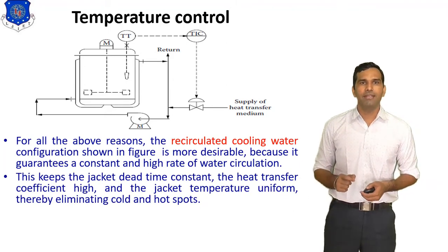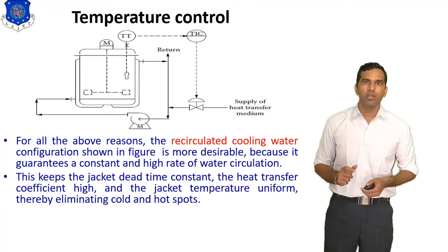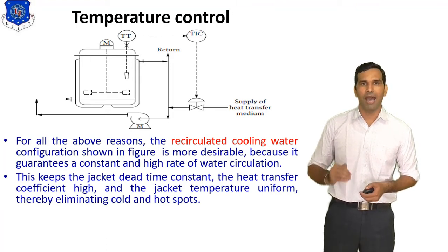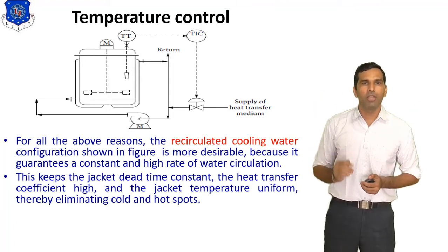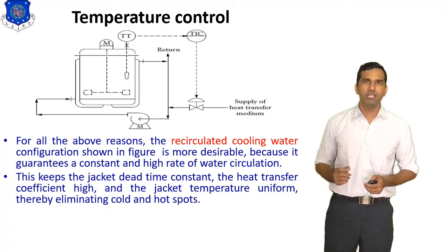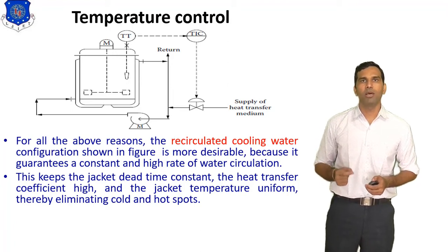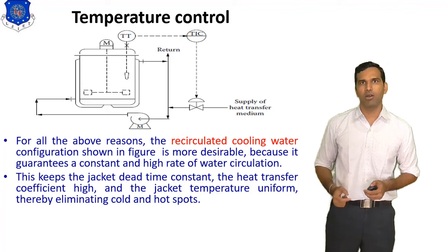This keeps the jacket dead time constant, the heat transfer coefficient high, and the jacket temperature uniform, thereby eliminating cold and hot spots. This is the advantage over the previous method of temperature control.